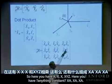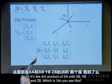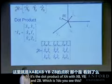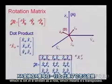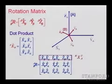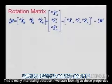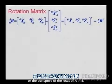xa, xa, xa. So it's the dot product of xa with xb, yb, and zb, which is, you see this? Which is xa and b written as a row, which means it's transpose. This is very interesting because if we start looking at these properties, we see that this rotation matrix is either the component of B in A or the transpose of the rows of A in B.